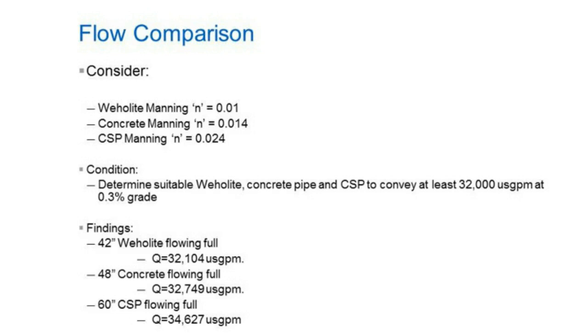We also want to keep in mind that HDPE is a homogeneous pipe that has the highest abrasion resistance of any pipe. This means when the pipe does become abraded, all you're doing is exposing more of the same HDPE material. Unlike CSP or concrete, the Mannings n is virtually never affected. This means over the life of the pipe, the flow will remain unchanged. And this is obviously very important in a culvert situation. The deterioration of the inside affects the flow rates and it can allow debris to get caught up and cause blockages, as well as reduce your overall flow rate through the pipe just from wear and tear.